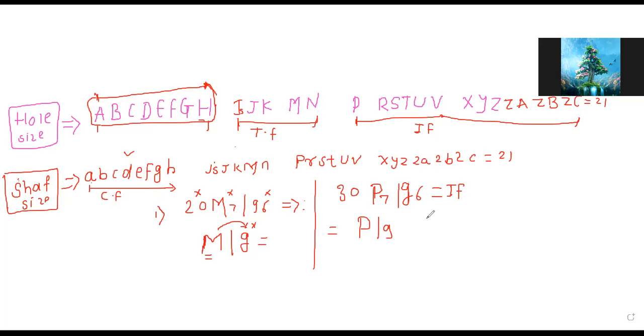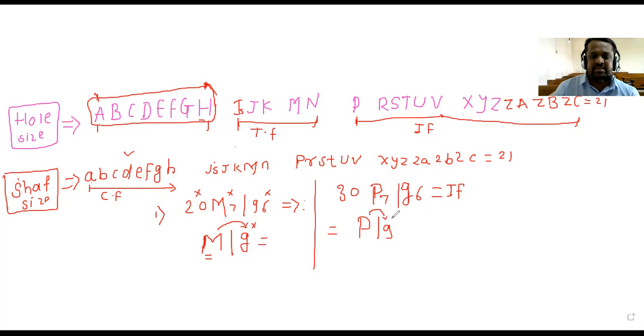Yes. The capital letter lies between P to ZC. Therefore, it indicates an interference fit. It means if the first initial capital letter is between these sets, it is not necessary to go to this side, so we have to check it. Yes or no?